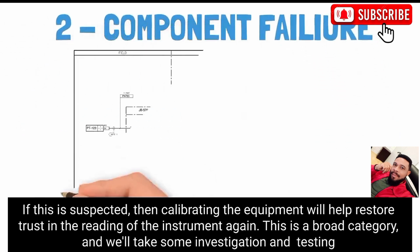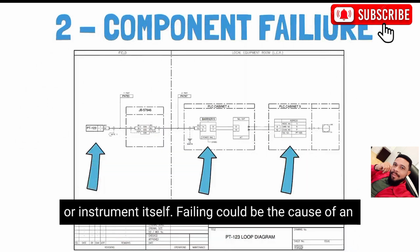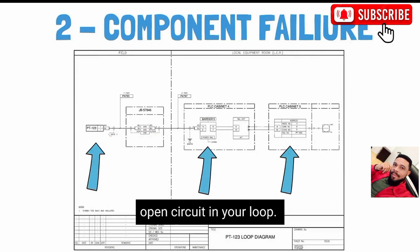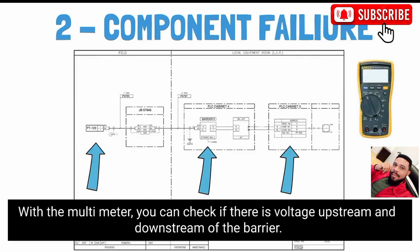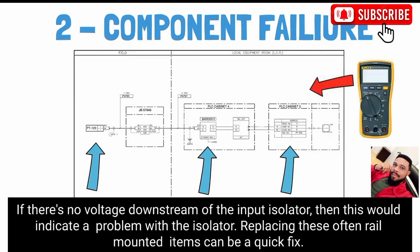Now, looking further, we can say that either the input card or the input isolator might be part of the problem, or even the instrument itself, that is causing this failure and is also causing an open circuit in your loop. With the multimeter, you can check if there is voltage upstream and downstream of the instrument. If there is no voltage downstream of the input isolator, then this would indicate a problem with the isolator.